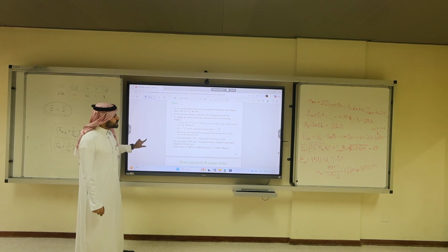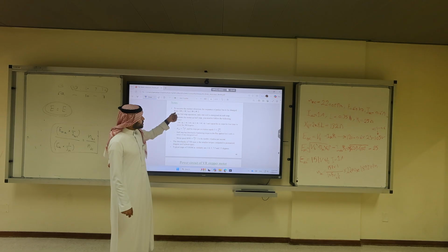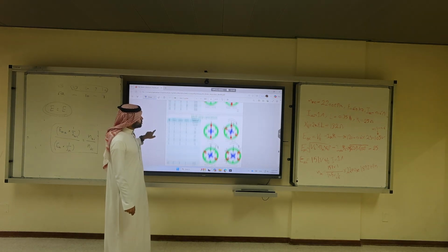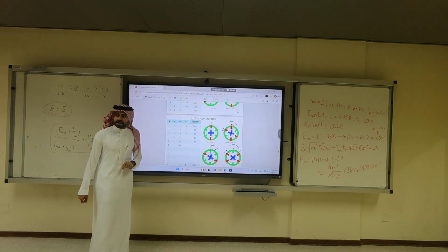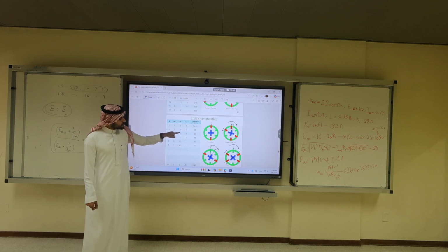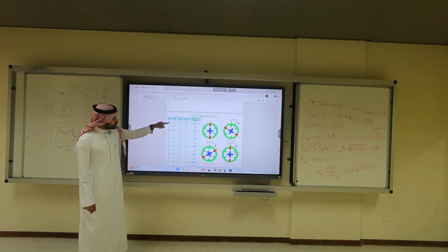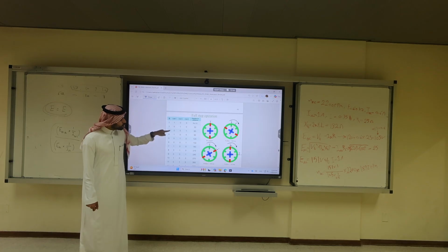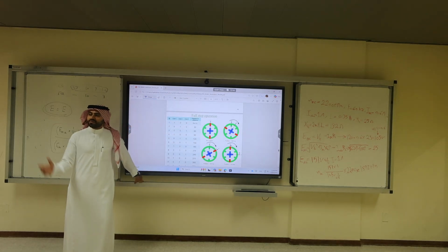These are the equations. To reverse the motion direction, the sequence of pulses has to be changed from 1, 2, 3 to 1, 3, 2. To reverse the direction, you just have 1, 3, 2, 4, 6, 5. Get it? So 1, 0, 0, then 0, 0, 1, then 0, 1, 0. If this is coil 1, coil 2, coil 3, it's like having A, C, B. Same phase sequence. Clear how to reverse the motor operation?